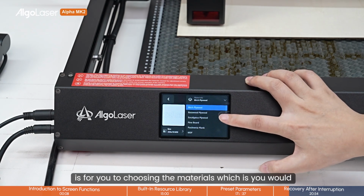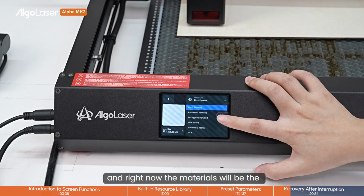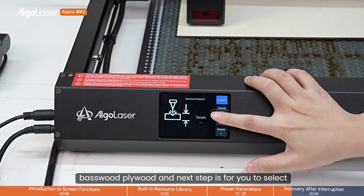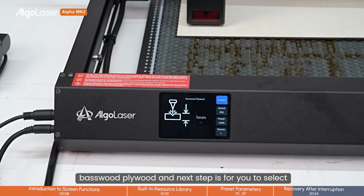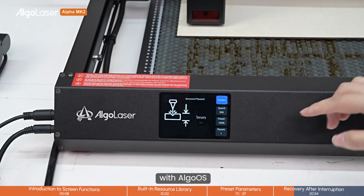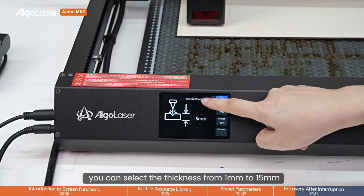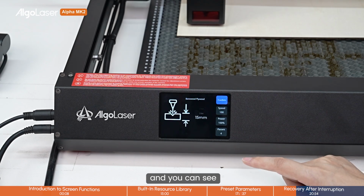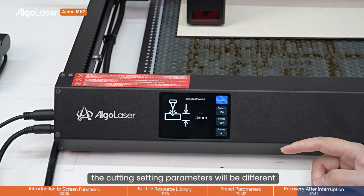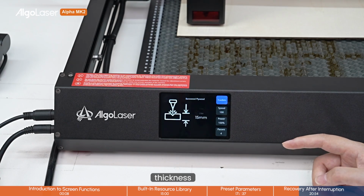It's for you to choose the materials which you would like to engrave or cut, and right now the materials will be the basswood, plywood. And the next step is for you to select the thickness that you need to cut. With AlgoOS, you can select the thickness from 1 mm to 15 mm. And you can see the cutting setting parameters will be different when you are choosing different thicknesses.